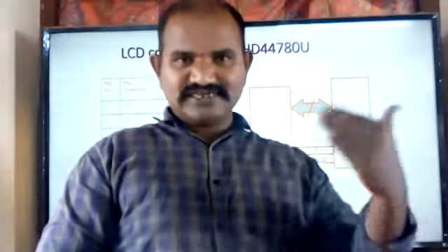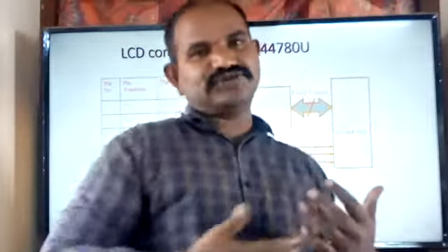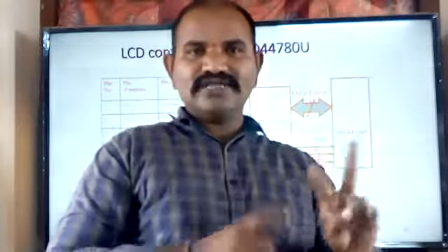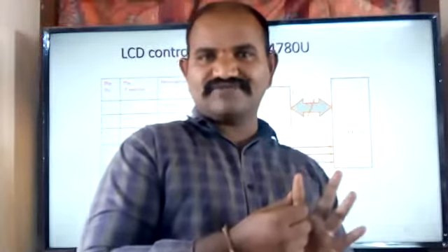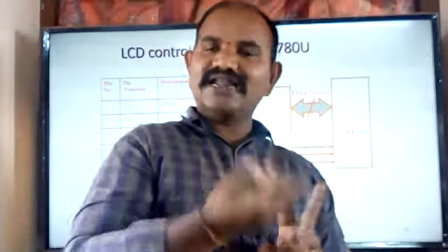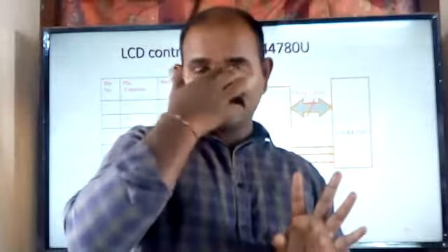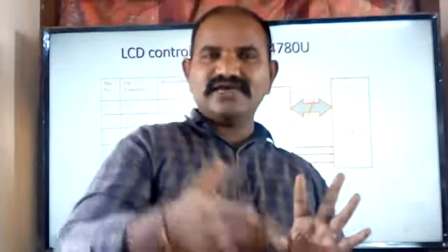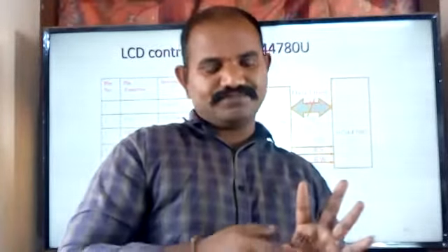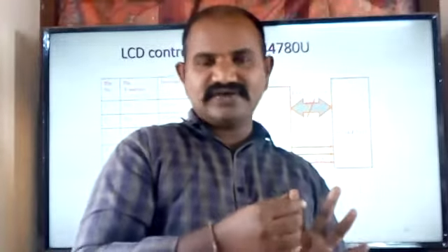And another method is, first of all, checking the readiness of the LCD module. If the LCD module is ready, then only send the information to the LCD module to display. Now, two methods are there. One is by using a fixed amount of delay, we keep on sending the information from the microcontroller to the LCD module. In the first case, we are not checking the readiness; we are expecting that the LCD module is performing its operation within that particular delay.